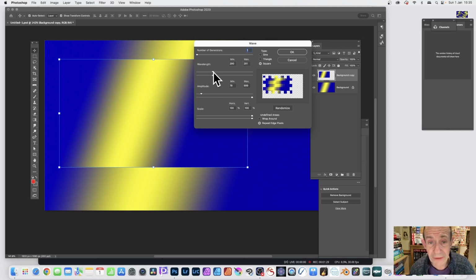You can change the wavelength, reduce it down, and you can see you get more of the squares. Unfortunately, there's no preview, but there's a preview here. So you can set the wavelength fairly low, and you get more of those squares or not. And also amplitude. And you can resize that, and you can see as you increase the amplitude slightly too great, you get obviously that result, which is not so great. Just reduce it down. So about 28, 20.